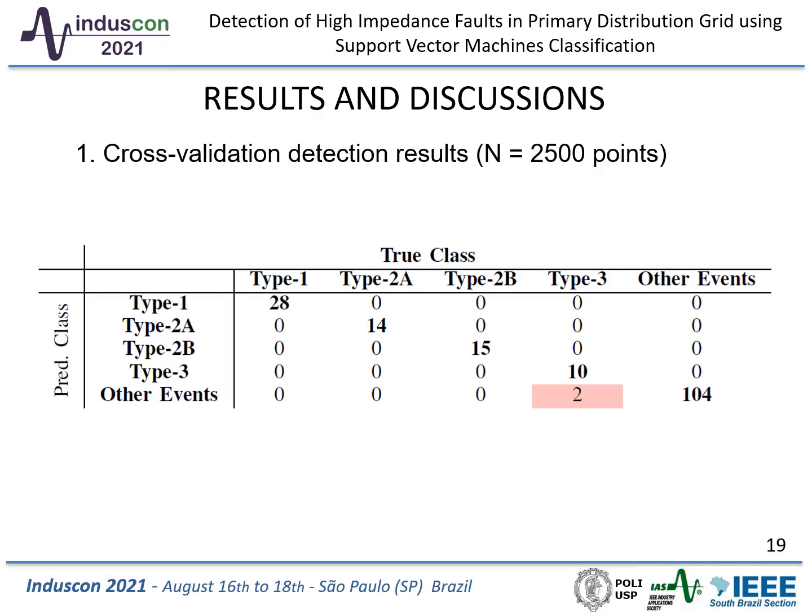The low amplitude of the current from type 3 faults makes the distinction between these faults and an event that causes imbalance very difficult. An important aspect of the detection strategy proposed in this work was to maintain a fault detection rate higher than 90%, while no transient event was configured as a HIF. This shows that feature extraction and selection were both properly conducted and that a significant classifier generalization capability was obtained.